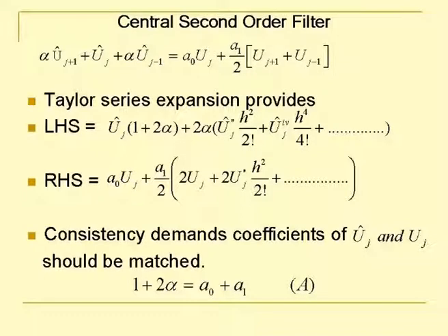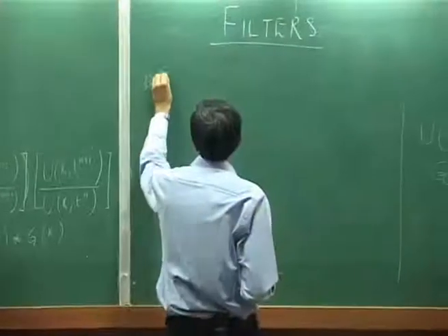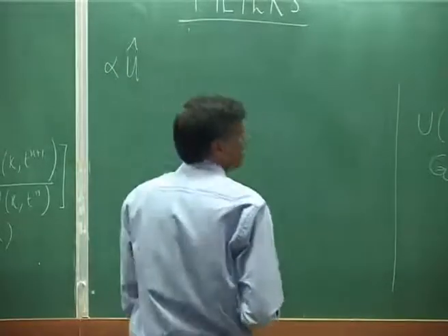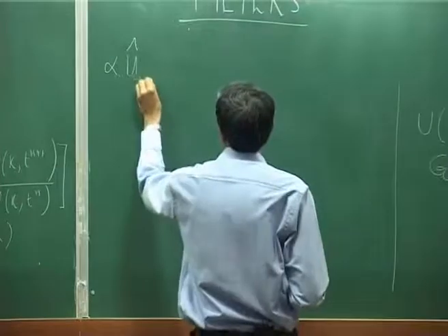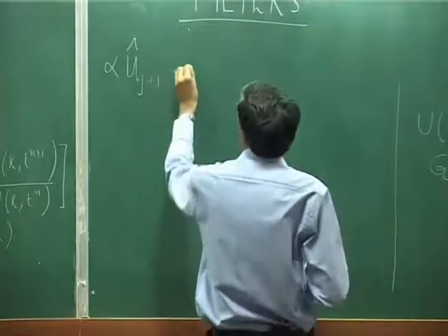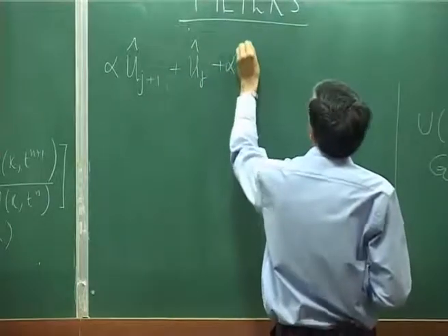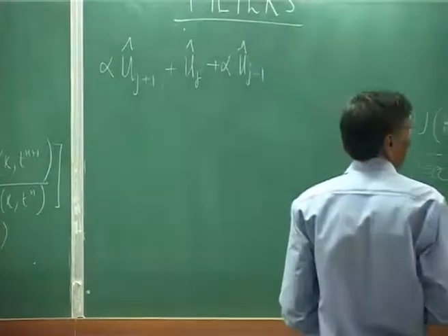The other one, we decided that the transfer function should be equal to 0 at the Nyquist limit. Okay. And how do you do it? Well, we have written down that equation that we see here. So this is basically that. Please do understand that this is written in the physical plane. These should be lowercase, although the slide shows them as uppercase, but this is what we are doing. So this is your filter.